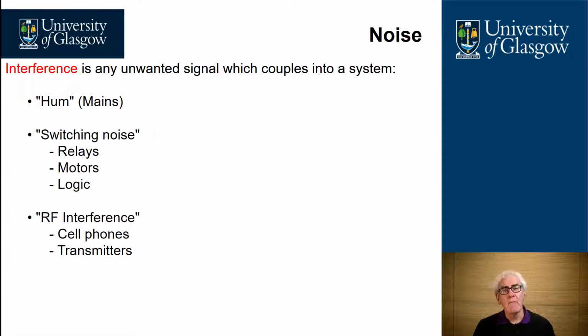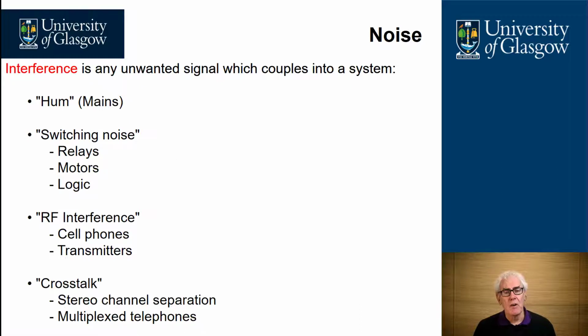It could be RF interference from powerful transmitters or cell phones that are nearby your circuit. These are all interfering things. And finally, it could be crosstalk from stereo channel separation. In other words, the left channel bleeds through into the right channel, or crosstalk from multiplex telephones where you actually pick up somebody else's conversation accidentally on the phone system.